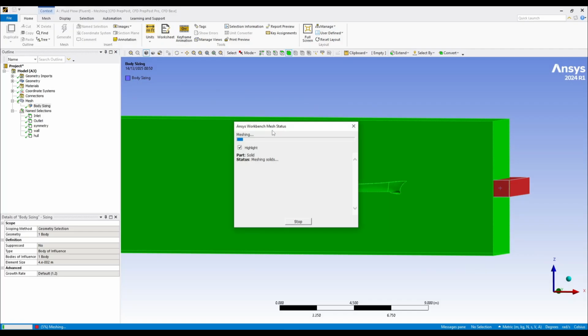Considering the project you're working with, the element size can vary, and depending on the input of the element size, the mesh can fail and be successful at the same time. So it's a very sensitive issue. You must always consider giving which element proximity, curvature mean size, and curvature angle the mesh is being successful.